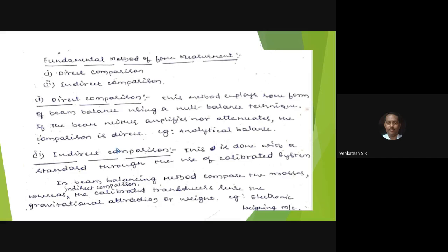Usually sensors are provided with strain gauges. These strain gauges convert the force into resistance. Resistance is converted into an analog signal, and the analog signal into a voltage signal. Again, that voltage signal is converted into digital form. You measure the weight of the vehicle along with the material in kgs or tons. Two or more translations are present, and the name itself indicates indirect measurement.